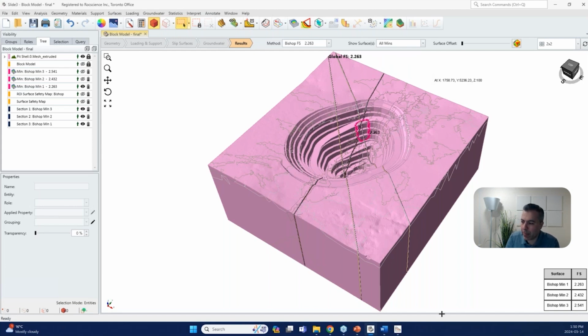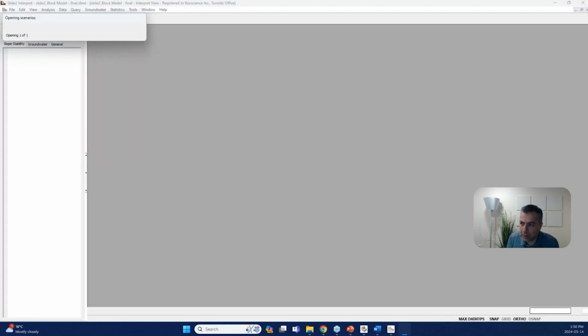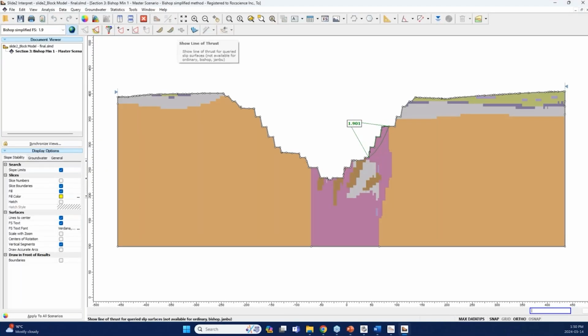It's within around 15% of the results of the 3D model. So the 3D model is larger by 15%, which is reasonable. Just keep in mind, when you have anisotropy in your model, the difference might be more than 10-15%, which is the typical range that we mention to our users.